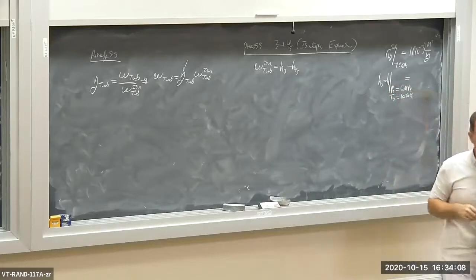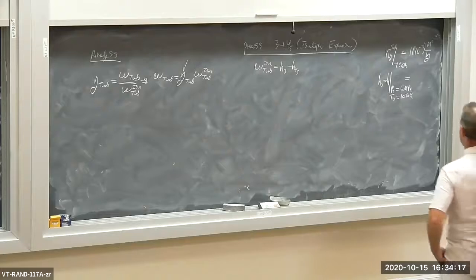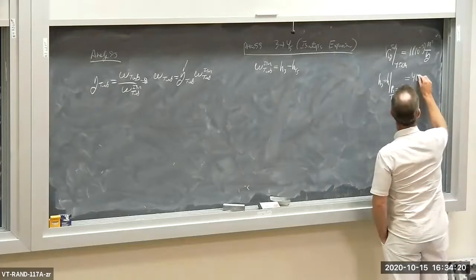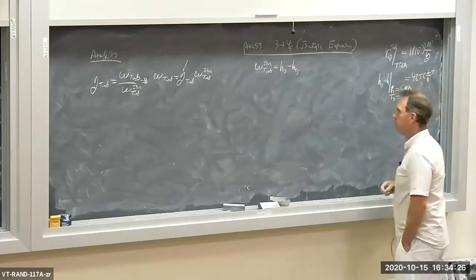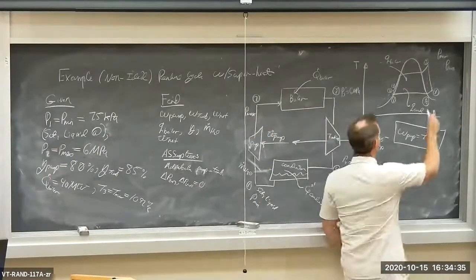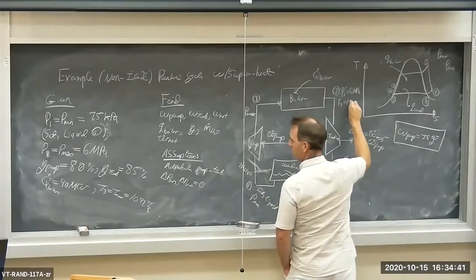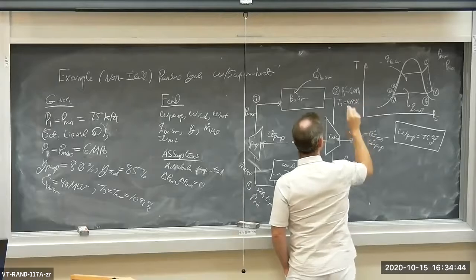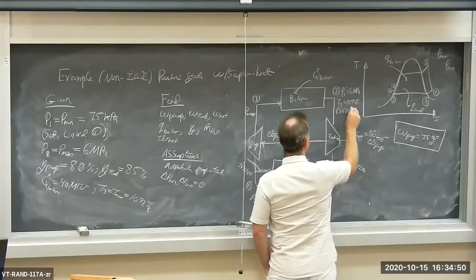You're going to find that you're in the superheated vapor region, and I get a specific enthalpy of 4856 kilojoules per kilogram. So indeed, this TS diagram, I drew it correctly the first time. You have superheat all the way up here. So T3 is 1092 Kelvin, okay? So it's a superheated vapor.